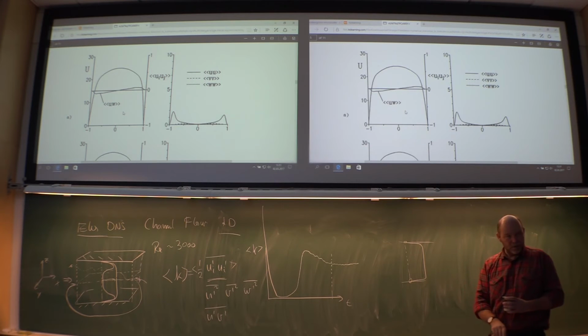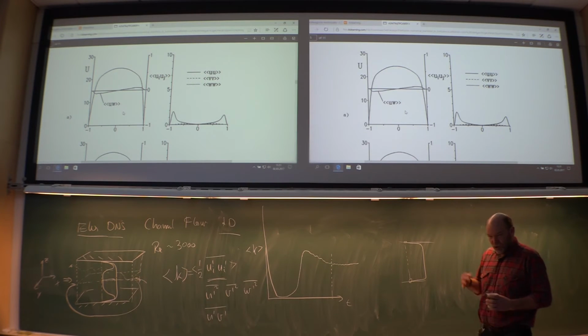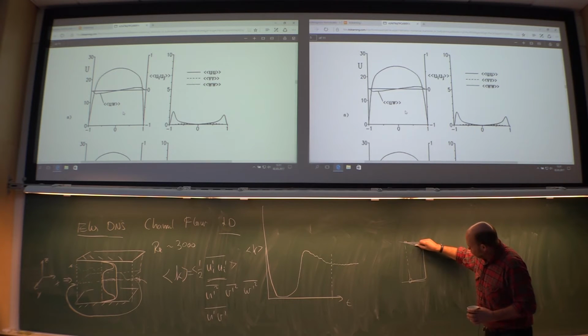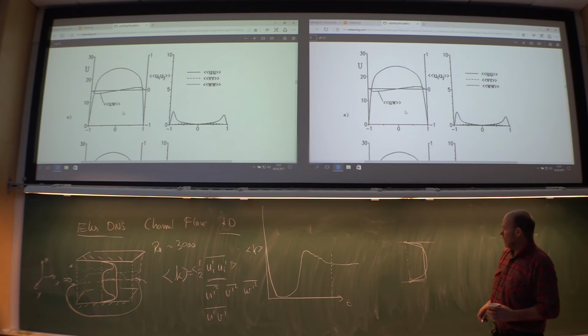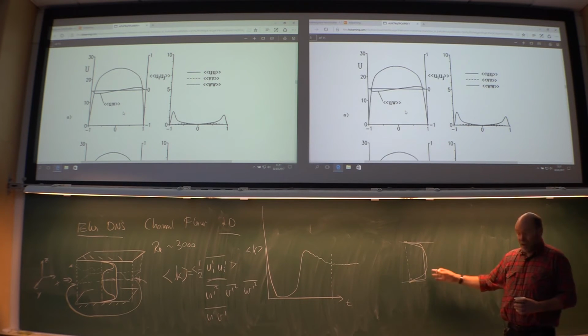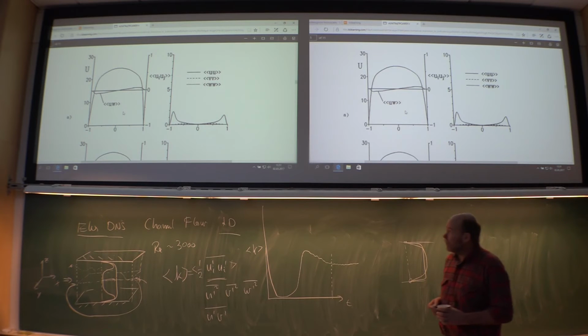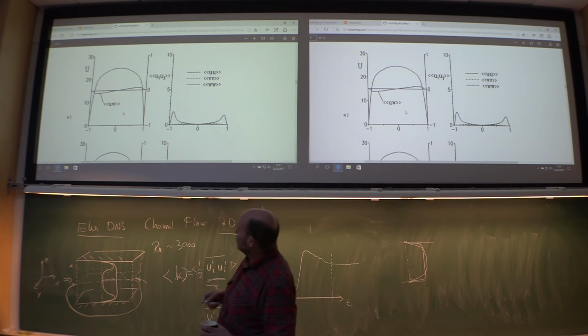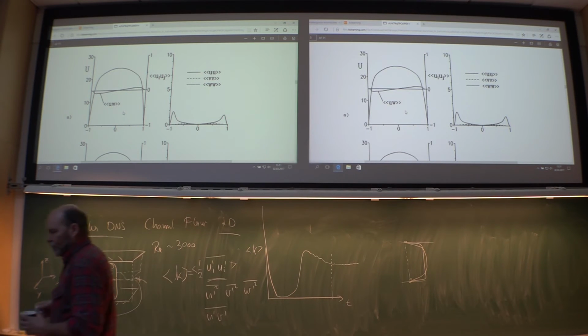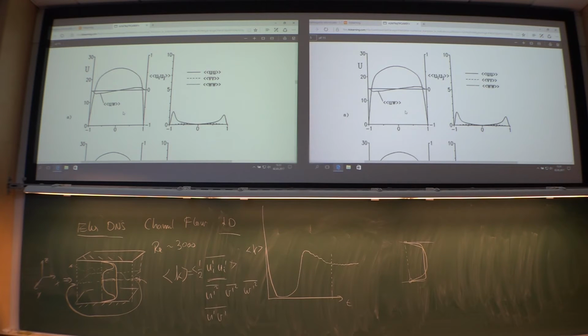That's very turbulent. If the Reynolds number is just turbulent, then the shoulders will be a little bit more something like that. Still not a parabola by all means, but the higher the Reynolds number, the sharper the shoulders, you might say, on the velocity profile. So you can tell from the initial one that it was not that high a Reynolds number, which was okay.